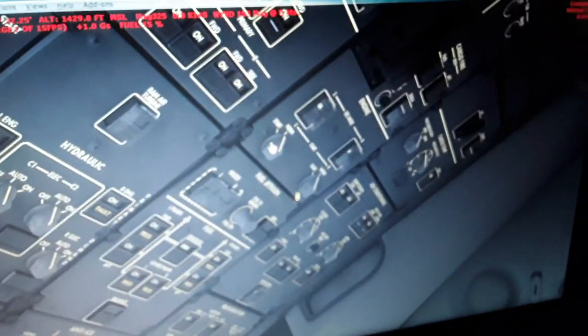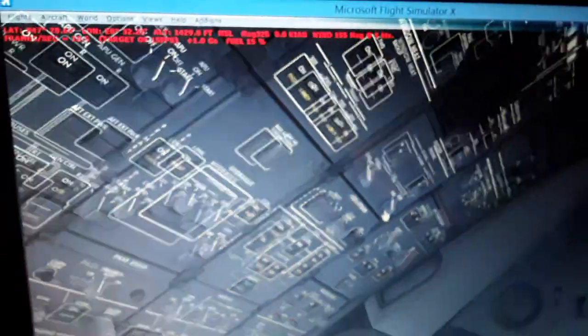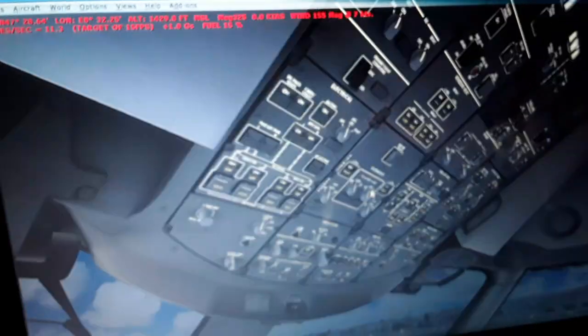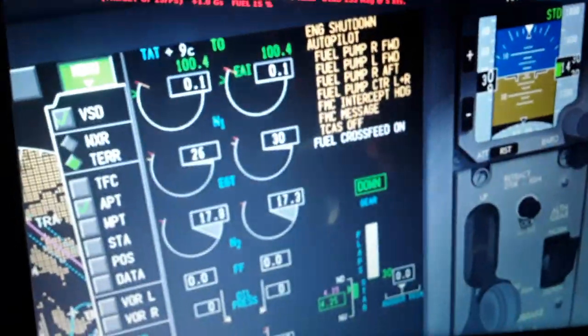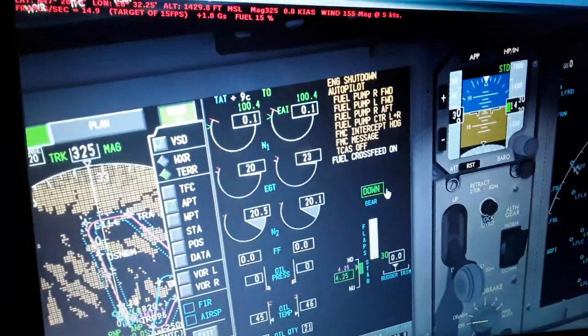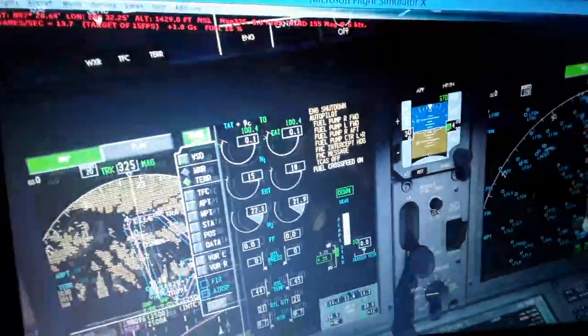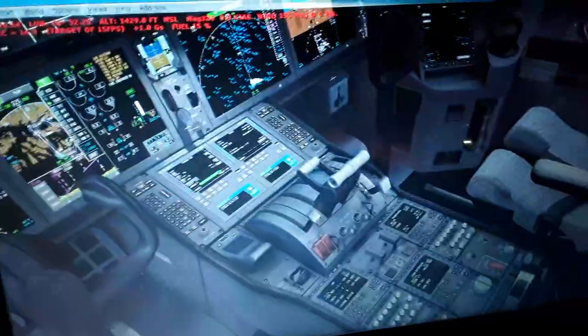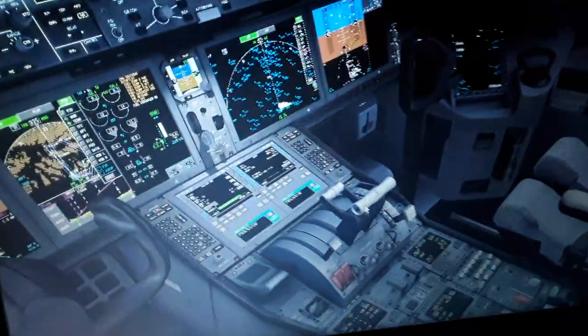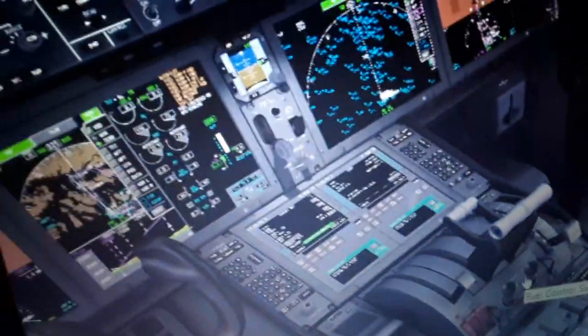So we have the engines auto start here. We turn both on. We're gonna have the automatic reset, everything in number, all lights in the overhead panel. So now we have pressurization from the engines. You're gonna see above 20% we can start. We have pressurization. We can start the fuel control now. Turn on the fuel, left and right fuel control. Fuel valves on.